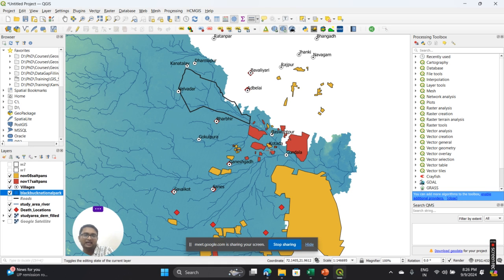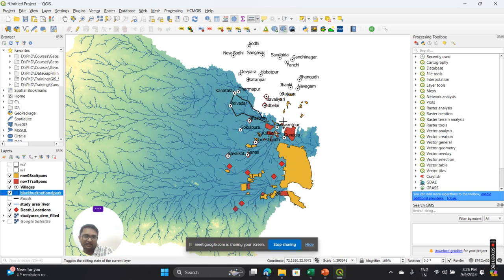And now they are also coming up with new highways around this particular area, which connect hubs like Ahmedabad and Bhavnagar and the rest of Gujarat. They have considered raising the highway elevation a little bit to make the natural flow of the river possible rather than blocking it. Earlier, construction was blocking the natural waterways, but now they considered that and created the highway at a bit higher elevation. So you can take learnings out of this kind of study.